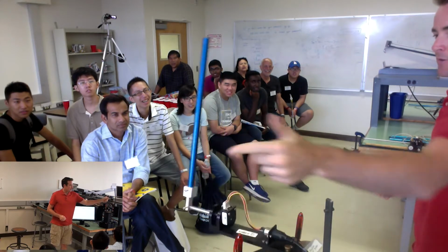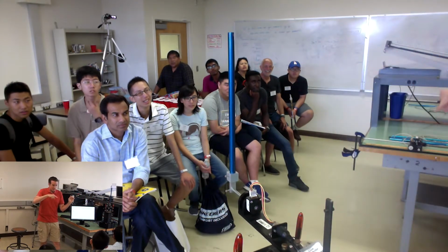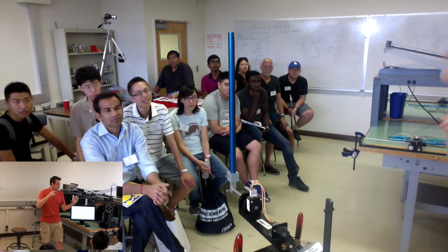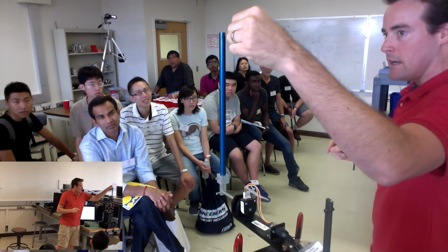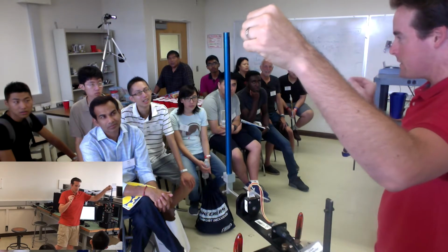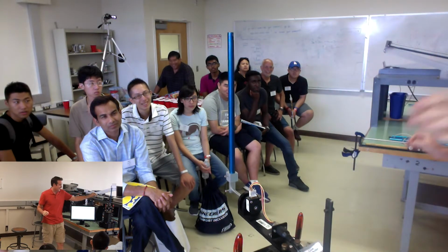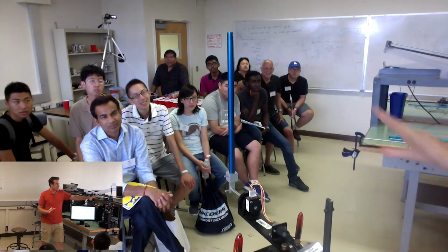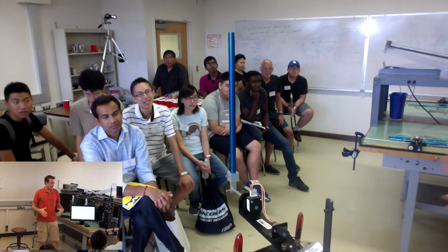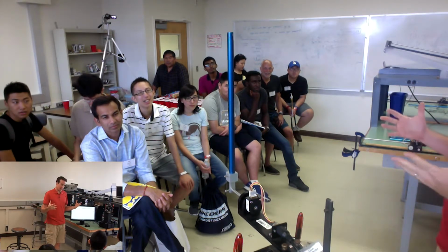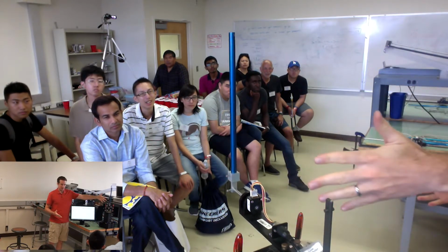It might tip over, but the point is this encoder here has 4,000 ticks, 4,000 measurements per revolution. It means that if you perturb this thing even less than the thickness of a human hair, the robot will know. The robot can handle it. So this is great because these things are way more precise than you as a human can accommodate. And you can leverage them with your knowledge of control theory. You can leverage these very powerful sensors and actuators that we have.